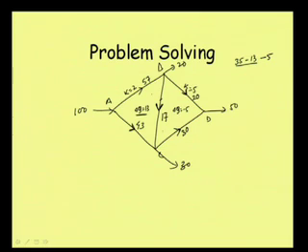Well, so like that we are getting the different flow distributed in this entire network. And now we can of course verify whether our condition is satisfied or not, because this is very important. We can check, 100 is coming in, 57 is going out, 43 is going out, and 43 plus 57 again is 100. So at this point the continuity condition is satisfied. At this junction, 57 is coming in, 17 is going out, 20 is going out and 20 is going out.